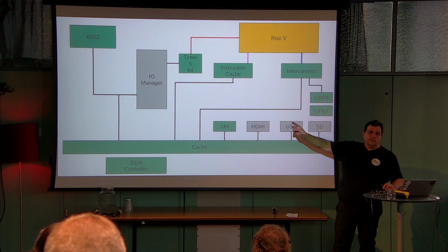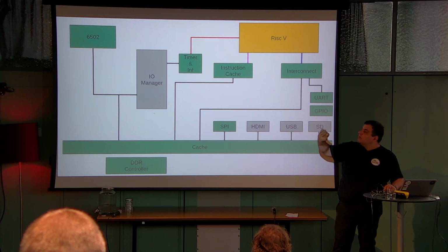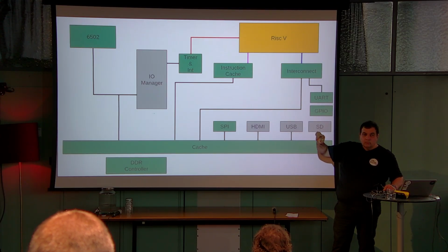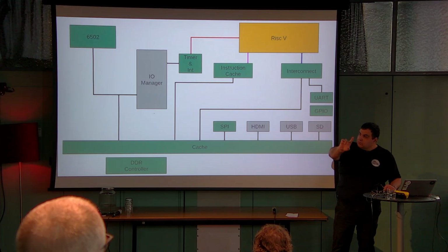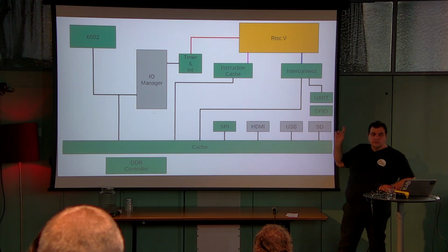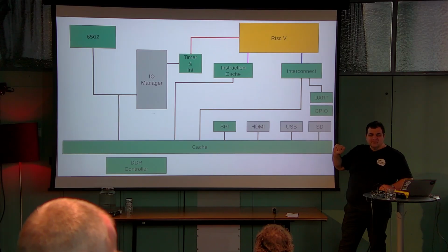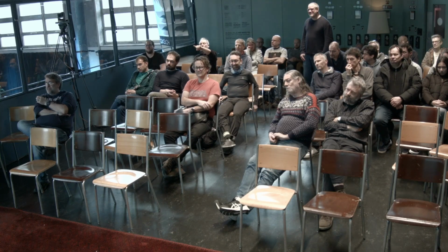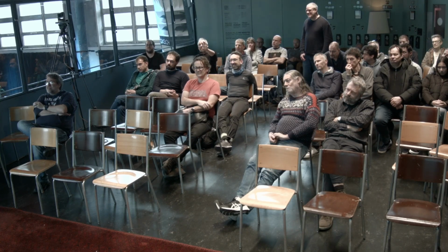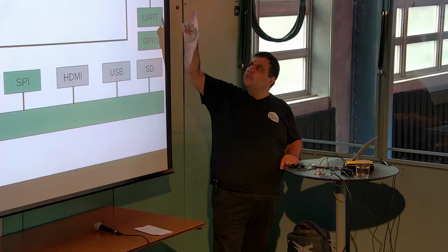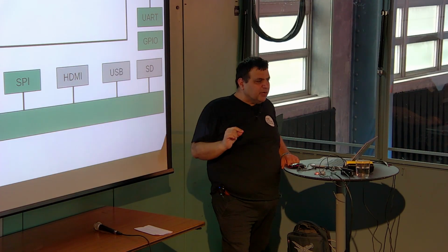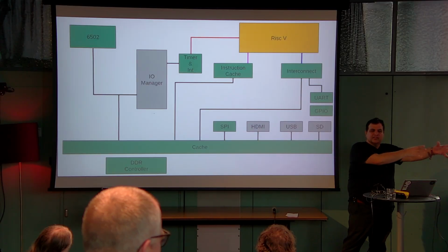Why would I want two FPGAs for that? So you will skip the RISC-V. No. One FPGA with all of this, including the RISC-V. Yeah, this 80,000 LUTs FPGA you have. 8,000. 8,000, yes. Because I thought the RISC-V you have there, the orange one, you will use as an external. The only thing that makes it orange as opposed to green is the fact that I didn't write it. I used an existing implementation.